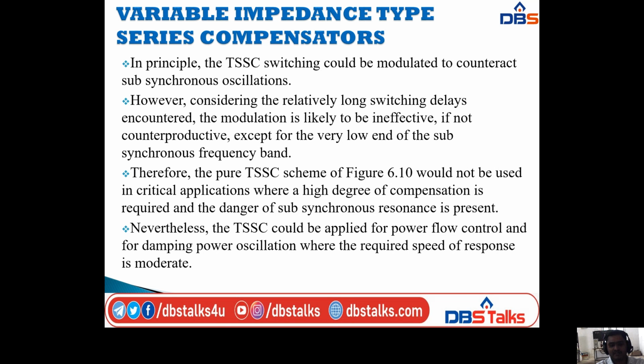However, considering the relatively long switching delays encountered, the modulation is likely to be ineffective, and it is not counterproductive except for the very low end of the subsynchronous frequency band. Therefore, the pure TSSC scheme of figure 6.10 would not be used in critical applications.